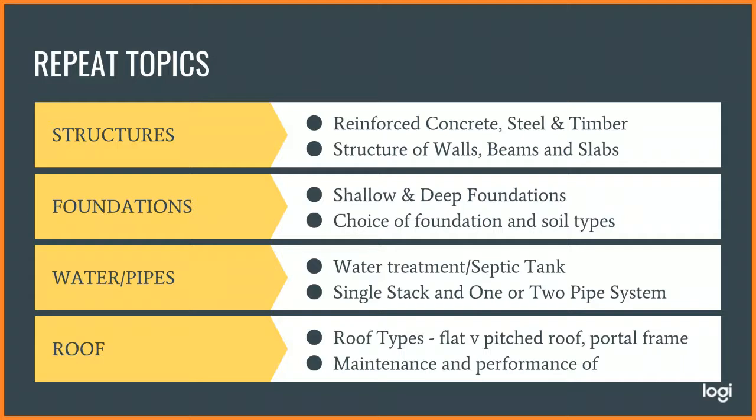So they may ask you to draw the roof, and after that they ask what type of material will be your choice for the roof. You can use metal base, or you can use tile base type of roof. A normal pitch roof in a residential area would be just the ceramic tile roof. But in more recent years, there is spandex, which is the metal roofing. One piece metal roofing is better, but the soundproof effect is less compared to ceramic tile roofs.